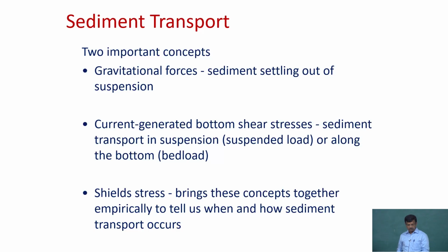On sediment transport, there are two main important aspects. Gravity always makes sure that a sediment is retained. However, the driving forces that we discussed now make the system move. So, in sediment transport we always look at two aspects. First, what is the minimum energy required to lift a sediment up? Till that time sediment will not move, even if sufficient current is there. So, a sediment has to be lifted up, then the current will do its job of drifting from one point to another point.